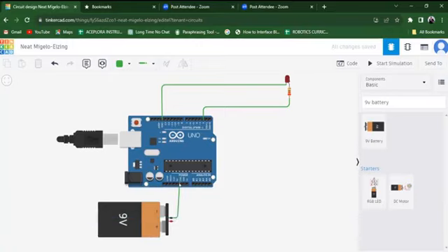Connect the negative to the GND as usual, the negative of the battery. And then we'll connect the positive to the VIN as I explained earlier, because this is a DC source. A battery has two terminals, right? The positive and the negative. So the positive goes to VIN of the Arduino, the negative goes to GND, right? So with that being said, we have connected this.